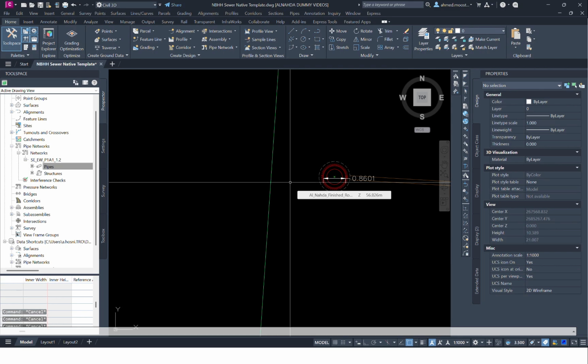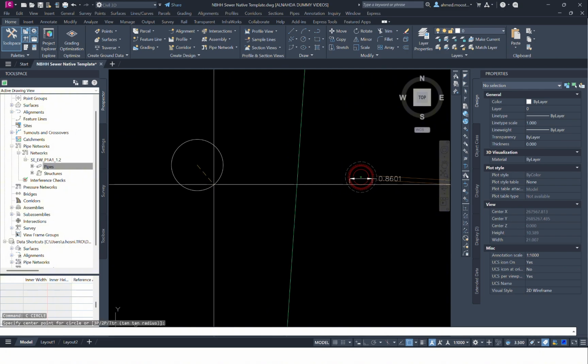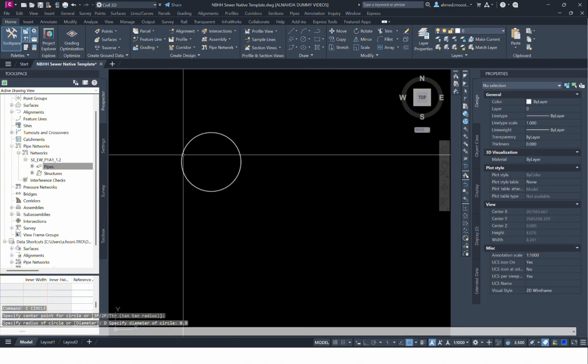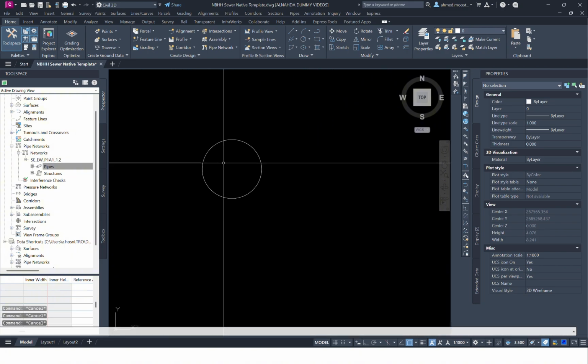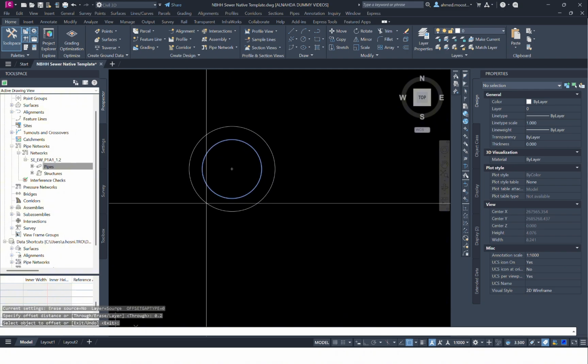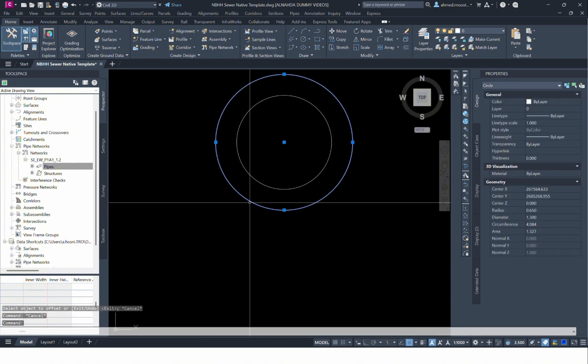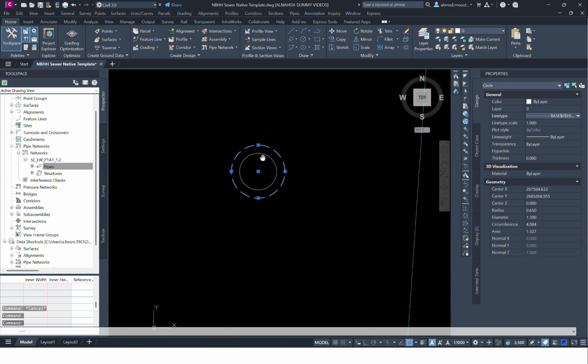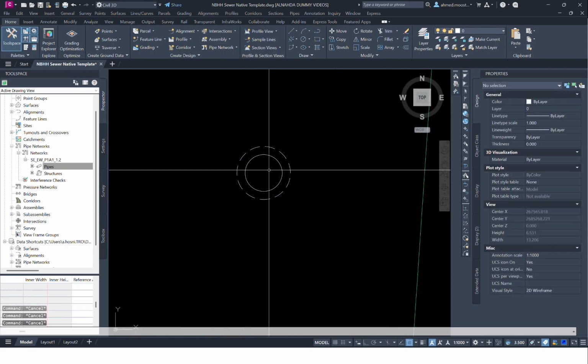If you have a 900 inspection chamber, you will just draw 900 and make an offset for the clearance. If you want 20 cm, like that, we can use this one as a dash line. So this is the clearance. I'm just giving a very simple example.